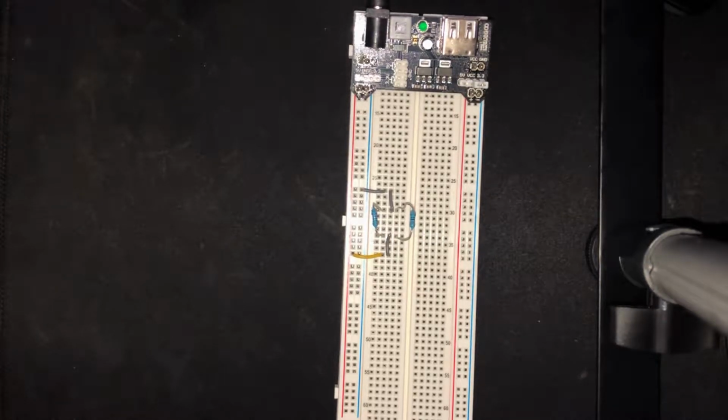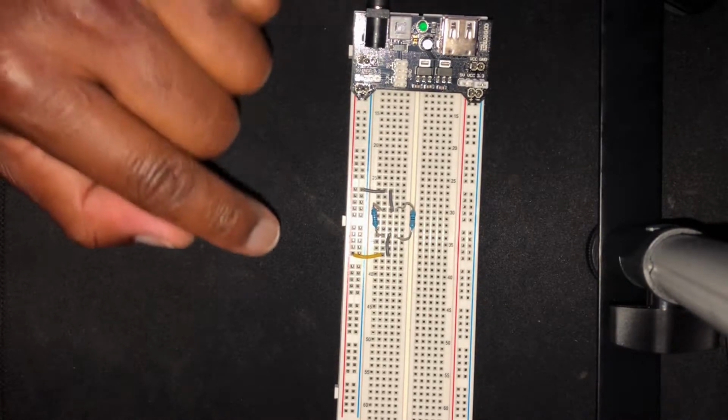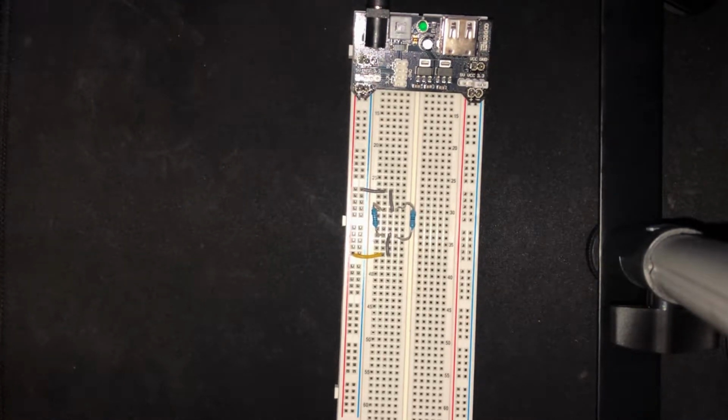Okay, so in the theory, we calculated that the total circuit current should be about 0.038 amps. I hope this will be easier to measure on this multimeter. I mean, it is a cheap multimeter, and current is not that hard to measure if you have a good multimeter, but I don't think this is a very powerful multimeter. It just does what it says. It tries its best. Then we also predicted that there will be 5 volts lost across each resistor, irrespective of